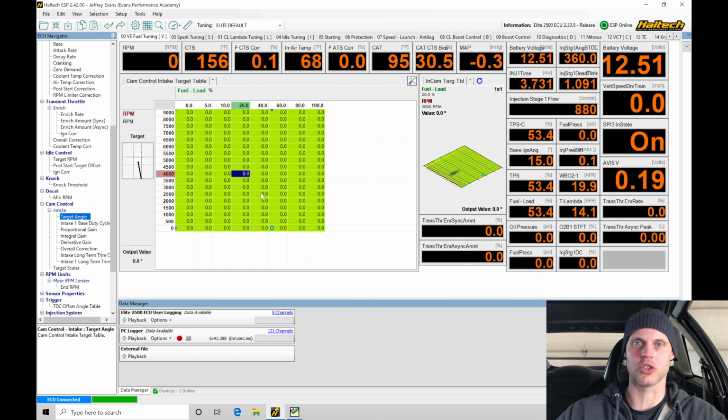So we're just, again, stripping away all the different layers of the way a K-series would operate. So the VTEC, the variable cam, those are going to be adding more confusion in here. So we're just going to be doing things one portion at a time in the calibration process, so you can see the cause and effect by making your changes, and it's going to be just simplifying everything. So you're not going to be doing everything at one time. So again, you'll understand kind of what we're doing and what we're accomplishing by changing the values.